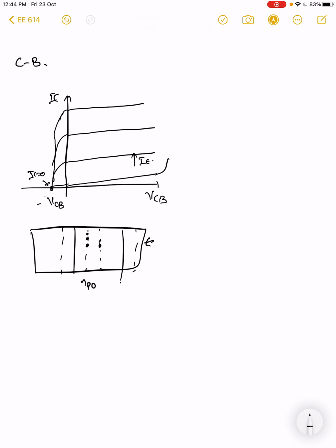What this condition is saying is that irrespective of what is my electron injection from the base, the total current becomes 0, or the electron gradient in the base becomes 0 at the same collector base potential, in the sense that my actual injection from the collector side is the same value, but still the gradient drops to 0 irrespective of my injection from the emitter, right? One has to wonder why that is so.